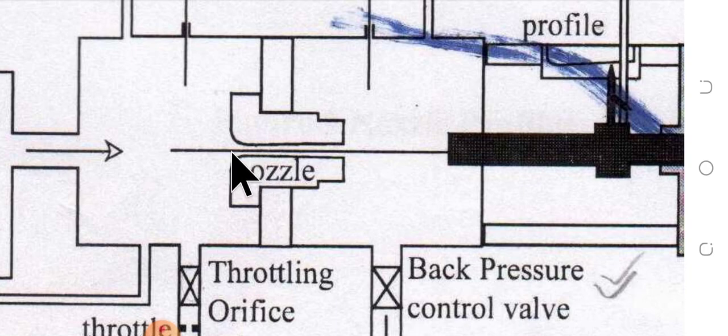But if the flow is not enough, if it does not go to the sonic velocity at the throat of the nozzle, then this divergent section works as a diffuser for a subsonic flow. So the pressure again rises and the velocity will decrease, because the diffuser will increase the pressure and decrease the velocity.